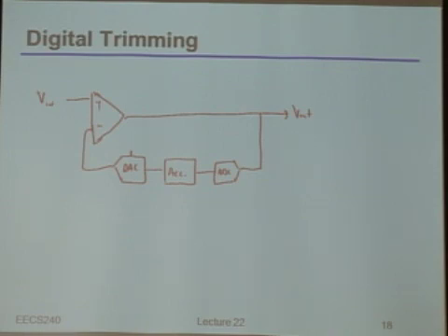The LSB has to be around your noise. Okay. You said it has to be around your noise. So that's maybe one way of saying it, although it doesn't necessarily have to be the same as the noise. But what's another way of phrasing that? Yeah, exactly. So the resolution of that DAC is really just set by what's the smallest offset you want to tolerate. Okay?